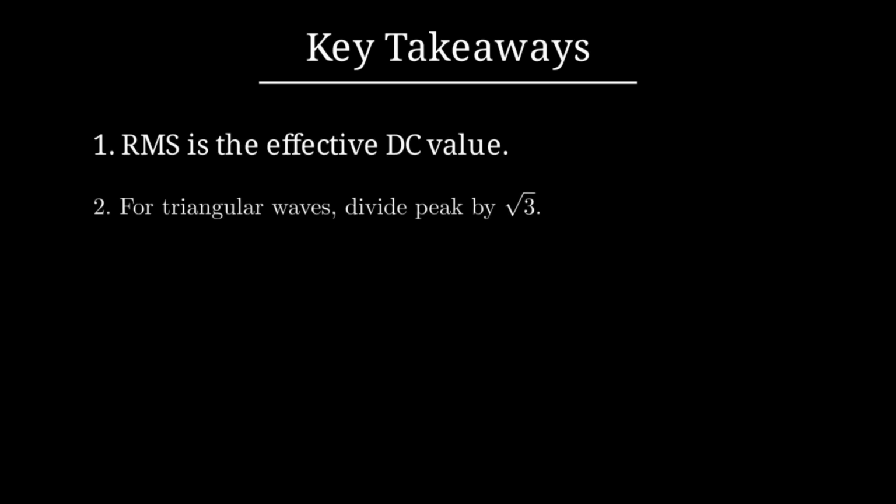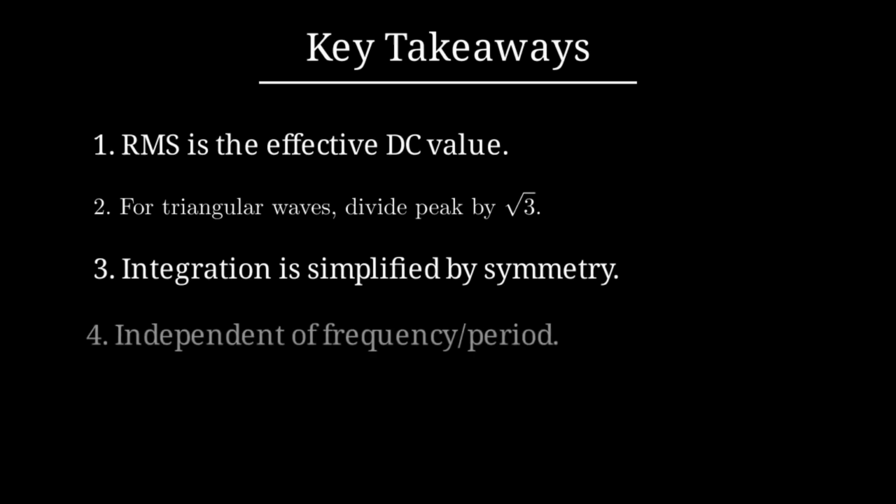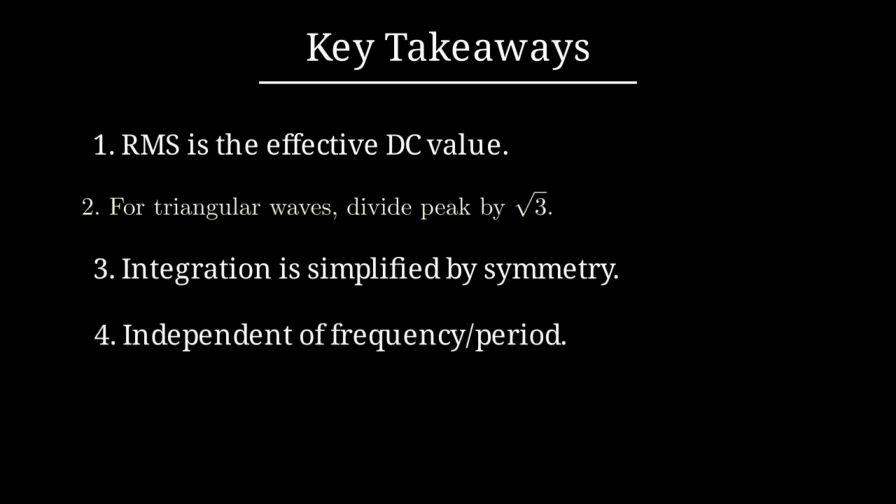Remember these key points: the RMS value represents the effective DC equivalent for heating. For any symmetric triangular or sawtooth wave, the factor is always 1 over the square root of 3, regardless of the frequency or period of the signal.